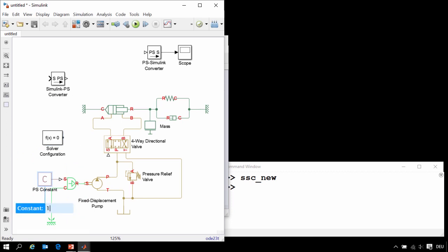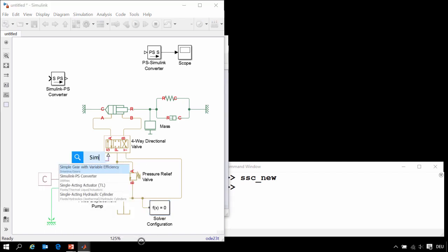And we will specify it to spin at its rated speed of 188 radians per second. Because Simscape and Simscape Fluids use solver technology above and beyond what is available in base Simulink, we will need access to additional settings. These we can access in the solver configuration block. The remaining input to our system is the position of the spool in the valve. We will specify that using a Simulink signal.